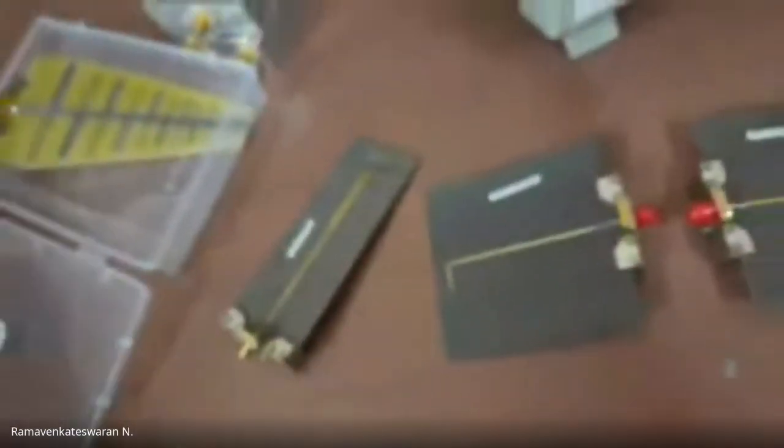You would have done this in the first simulation experiment. This is exactly the Yagi-Uda antenna, with more elements in a straight line. This is what was used in the olden Doordarshan TVs. And this is like a log periodic antenna. So you will get a higher gain in these antennas. Basically, these antennas are printed onto the substrate. So this is a broad picture, and let's come to the horn antenna.